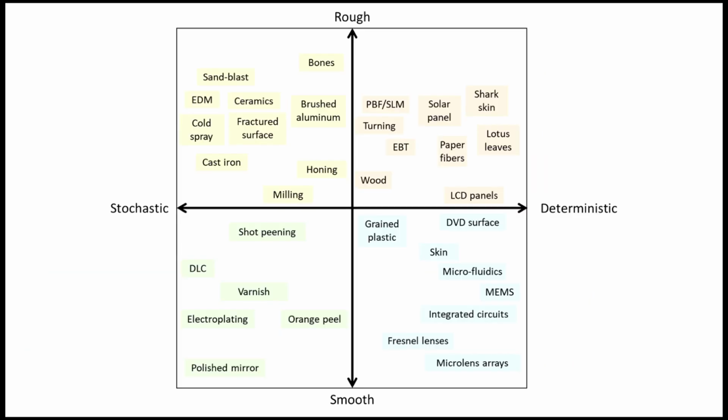Each manufacturing process creates a specific surface, like a signature that is characterized by its own complexity and isotropy. For example, turning, grinding, or polishing usually produce simple, directional surfaces. In contrast, electrical discharge machining, brushing, additive manufacturing, or laser texturing generate more complex and often anisotropic surfaces. Each material, each process is associated with a specific surface topography, with its own complexity.